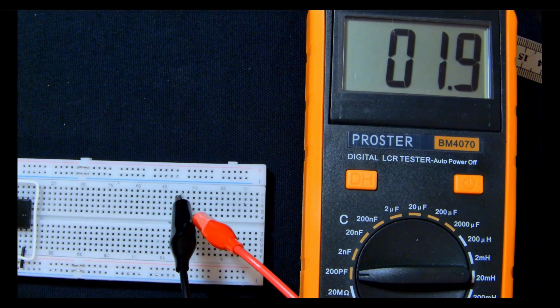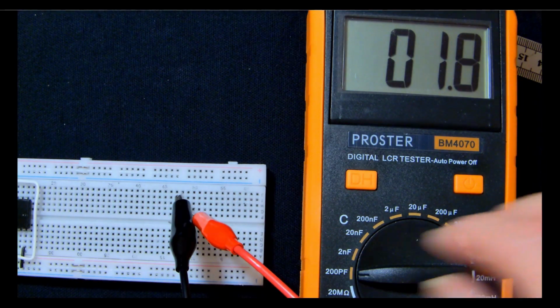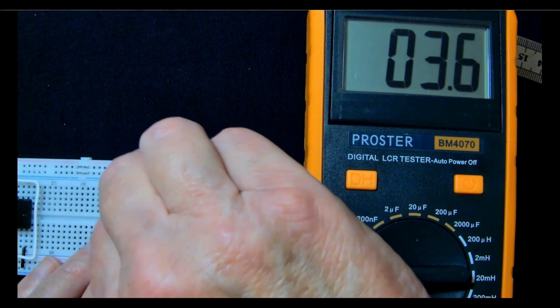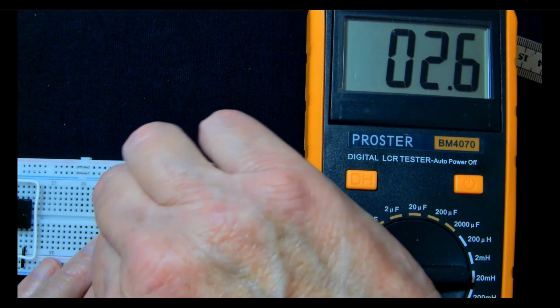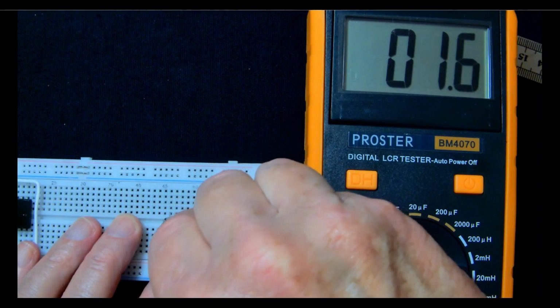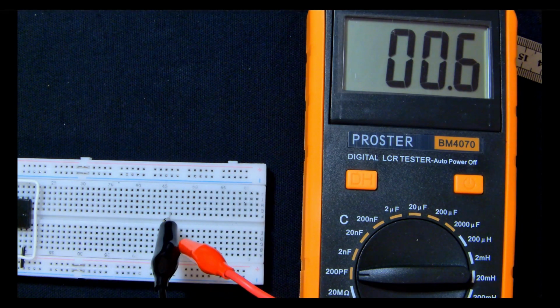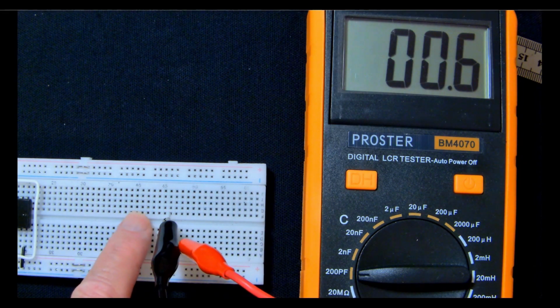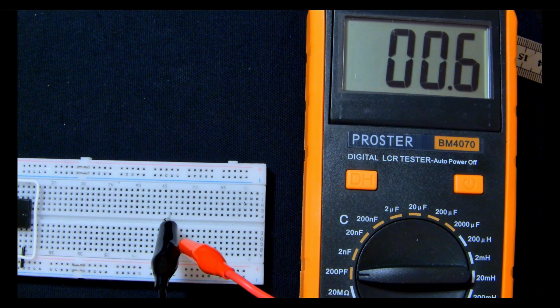Now, admittedly, that's a very, very small capacitance, but if you're dealing in high frequencies, this can make a difference. So let's try two opposing. That's even less. So I'm going across the gully now. That's just over 0.5 of a picofarad, which is really tiny. So you can see that this exists for real on the board.